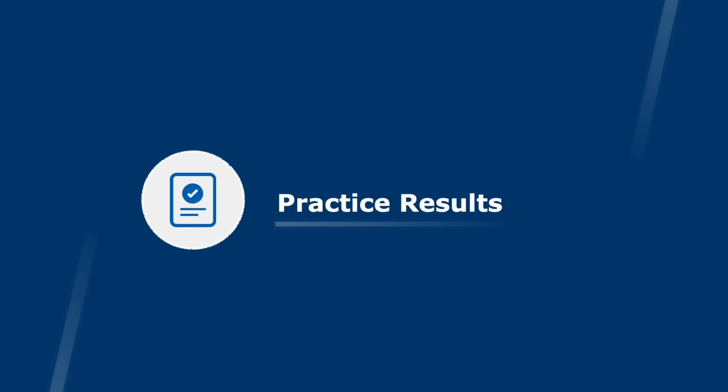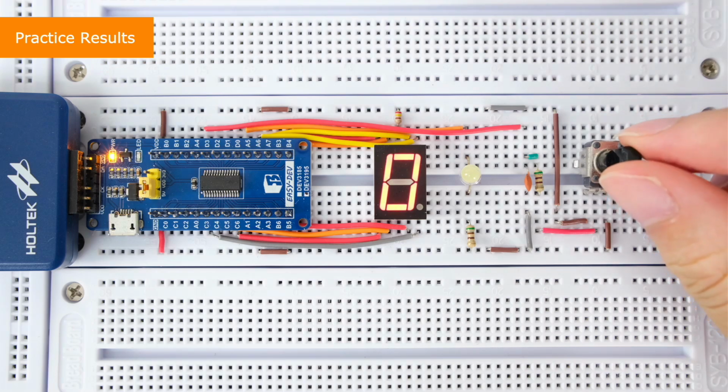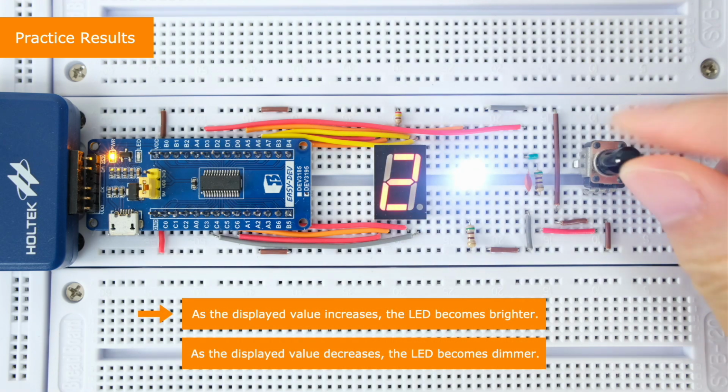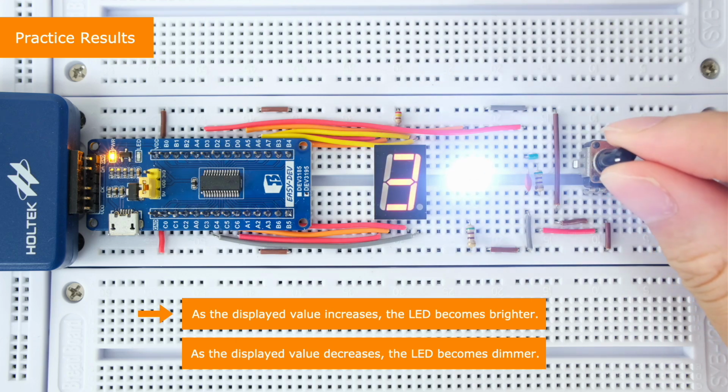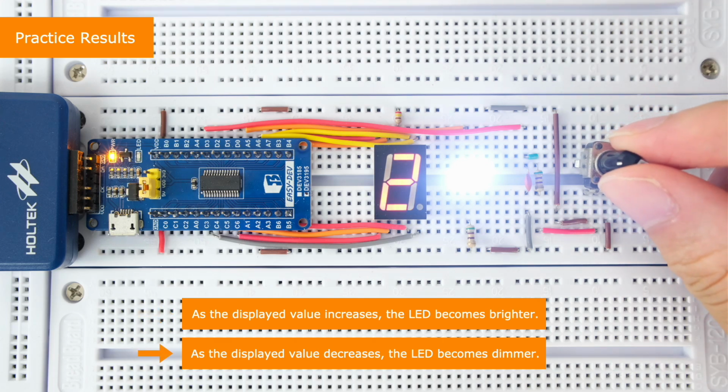Practice results. After the MCU is powered on, a display of 0 on the digital tube indicates that the current LED is off. The value on the digital tube represents the LED brightness level. When rotating the potentiometer, it can be observed that as the displayed value increases, the LED becomes brighter. Conversely, as the displayed value decreases, the LED becomes dimmer.